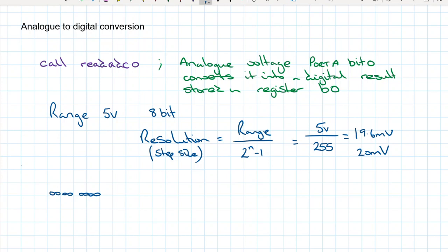if we have an 8-bit value, all the zeros, then the analog input value could be anywhere between 0 volts and approximately 20 millivolts. And then the next step from that is when we get a 1 out from the conversion, and that could be anywhere from 20 millivolts up to 40 millivolts, etc., etc. And we keep going up, so that's why sometimes it's called step size.